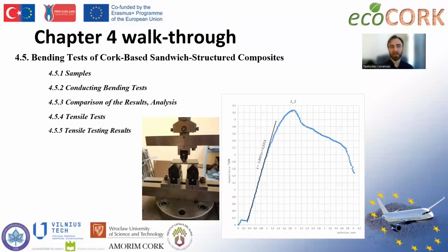In the last subchapter, 4.5, bending tests of cork-based sandwich structure composites, you will see the information about the tests that we performed during this research. The samples that we used were very similar to the ones used in the harmonic modal testing. So we had 3 sandwich plates with cork composite filler and glass fiber reinforcement, and they were compared between themselves and also with foam filler material with glass fiber